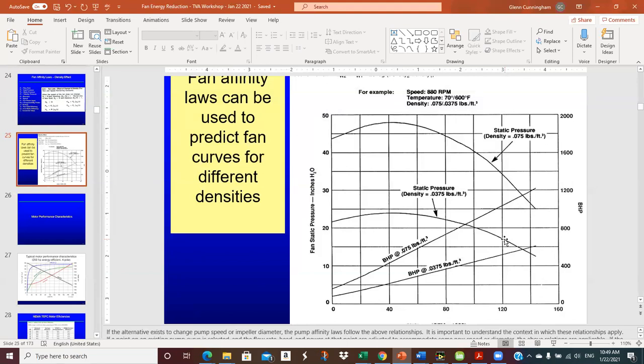Okay, I had a little trouble understanding, but was that in terms of taking flow measurements? Right. Okay. Well, rectangular or round doesn't matter. What you want is a good long straight section of duct, if you can find it, so that the velocity profile has become as uniform as you can get it. So you don't want to be right after an elbow or right before an elbow.